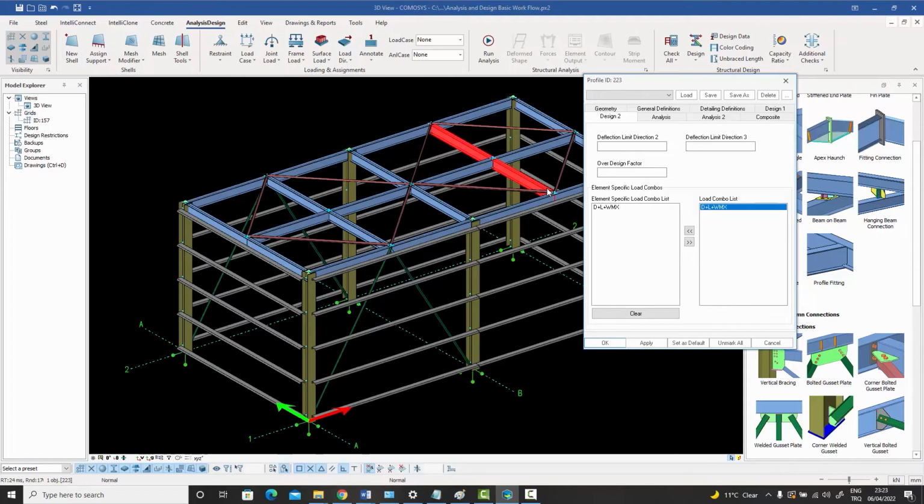And this is useful when you're dealing with specific cases. For example, most standards will want you to use a particular wind load for the entire facade. So they will say that for the facade up to a height of, say, 10 meters, use a wind pressure of 50 kilograms per square meter or 80 kilograms per square meter. That's for the whole facade. But then they will also add that for individual girts, use a slightly higher load, not 50, but they'll multiply it by a factor.